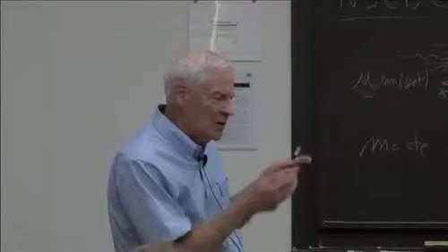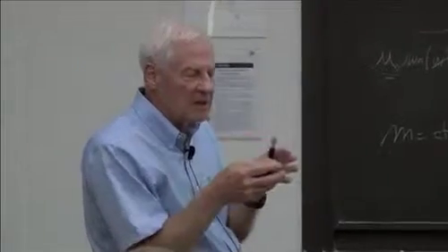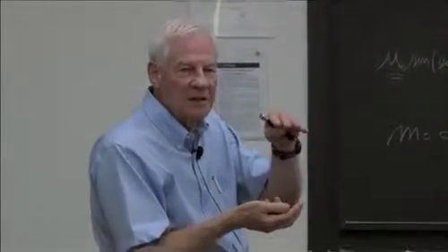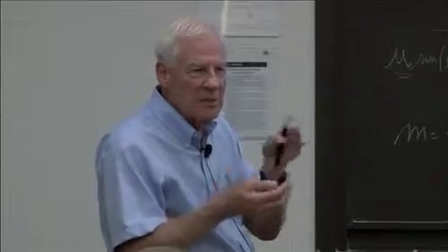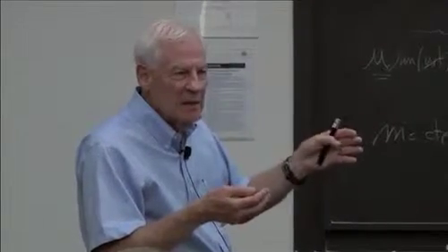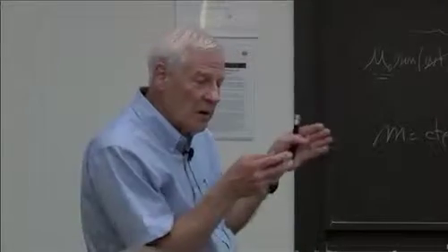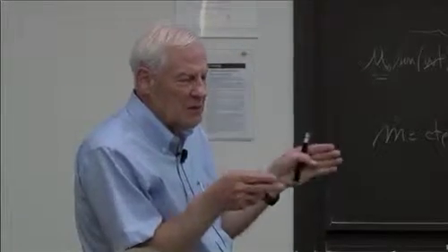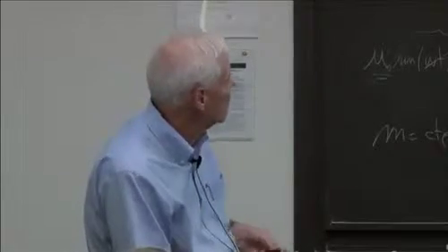But the fact is, when you have energy released behind this reflected shock wave and it starts to ignite and release energy, what's happening? It's not constant volume. One boundary is a shock wave. Pressure starts to build up, tells that shock wave to speed up. It's not a constant volume problem. So it's modeled that way, and you can get away with it sometimes up to the time of ignition, but then you're done. You can't model anymore because it is not a constant volume problem.